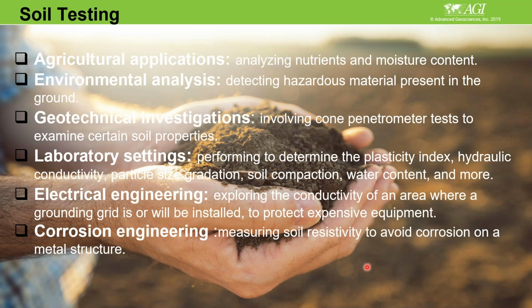Geotechnical investigation is where most of you have been using this technique, but there are also some 4-point or multi-electrode measurements like a CPT measurement that you can do with this resistivity imaging, and I will show you how you can do this with our system. Typically CPT is a cone penetration test.